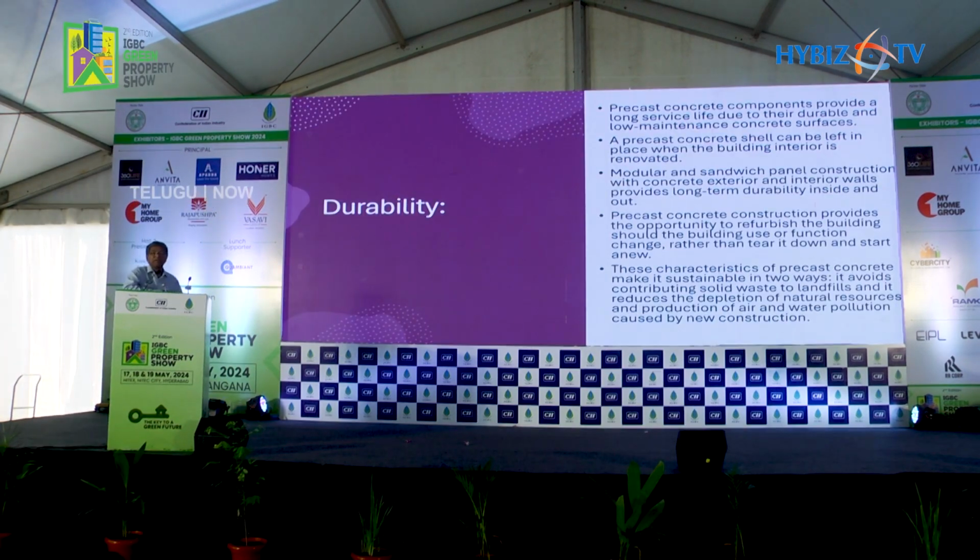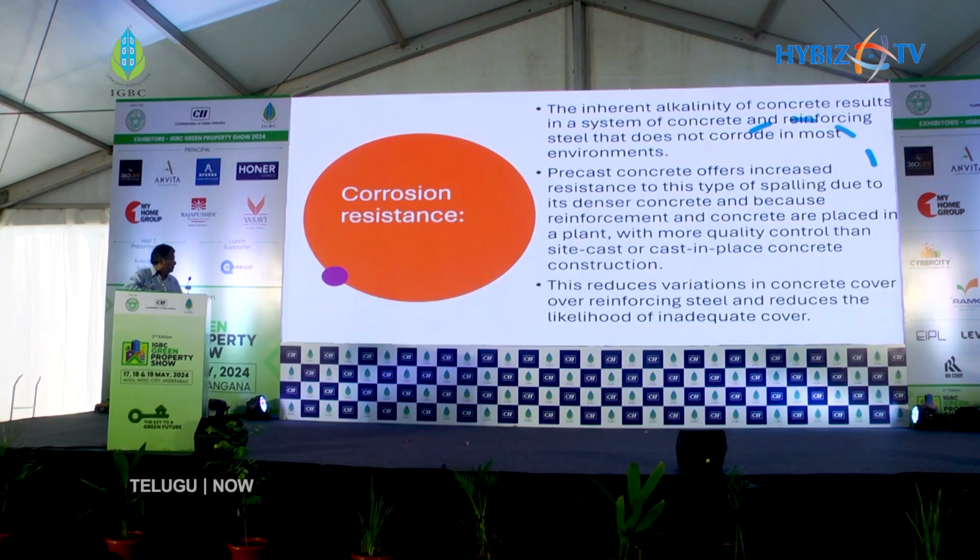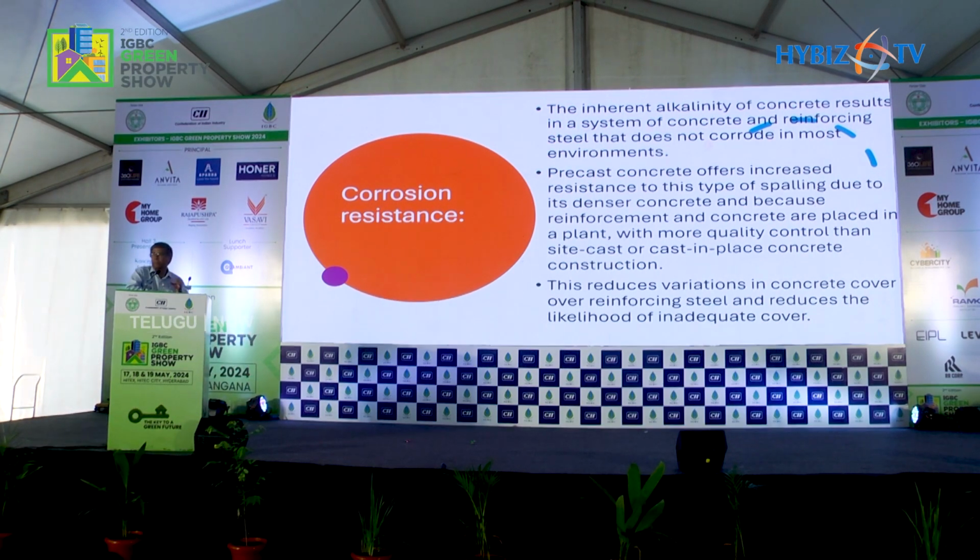Durability: it is more durable because of precast concrete walls and modular elements that are repeated in the production, and that gives a very good edge over in-situ construction. Being produced in the factory, precise covers are maintained. Quality control is very precise, whereby your elements will have a very correct cover and very good corrosion resistance to the steel, right?